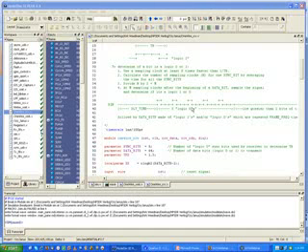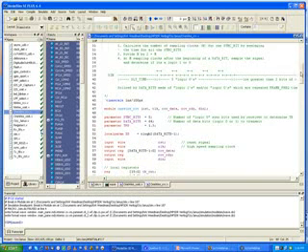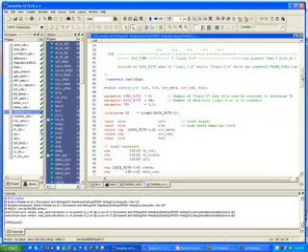Okay, so we have the 5 quote logic zeros, and then there'll be a low that's greater than 2 bits of time, and then that'll be followed by the data bits, which will be quote logic ones or zeros. And of course you could do your own method. This is just a method I chose.